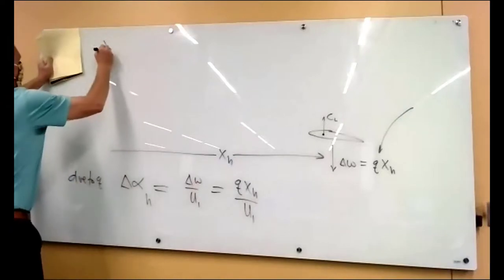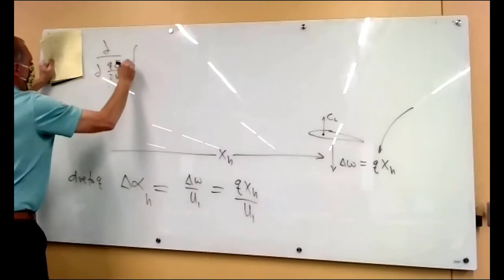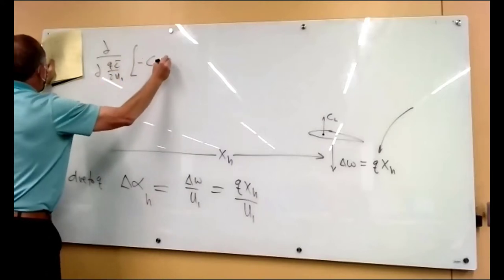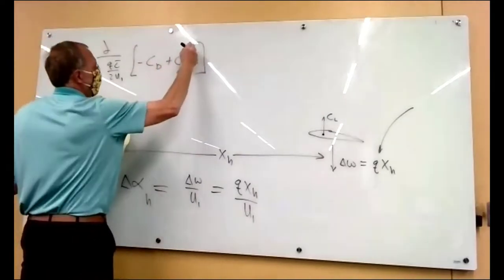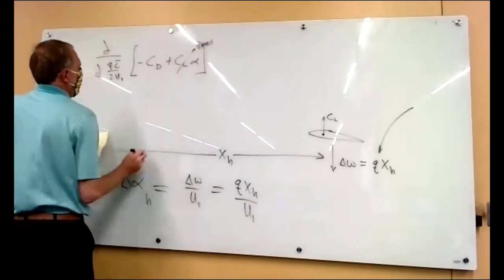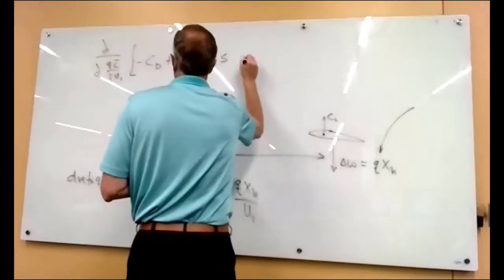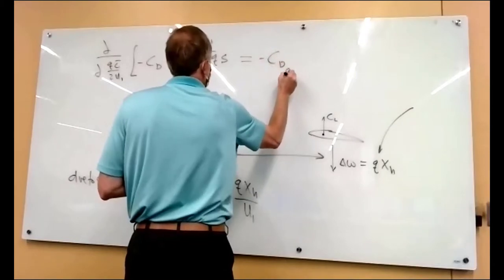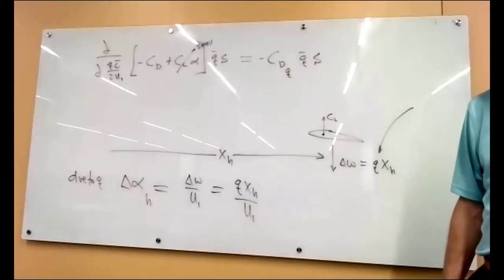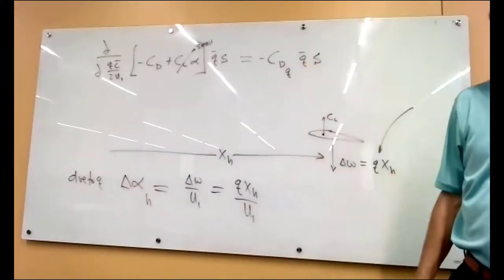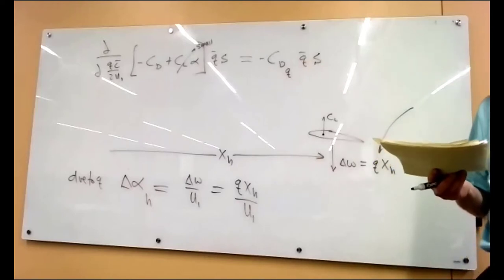So we're taking the derivative of our normal formula for FAX. And again, we're going to say this is small because alpha is small. And so we just get the derivative of CD with respect to this thing. And since we can't really go any further than this, we'll just call it CDQ and say, well, we need some kind of wind tunnel data that tells us what that is. And there are wind tunnels where you spin your model and it gives you these derivatives.